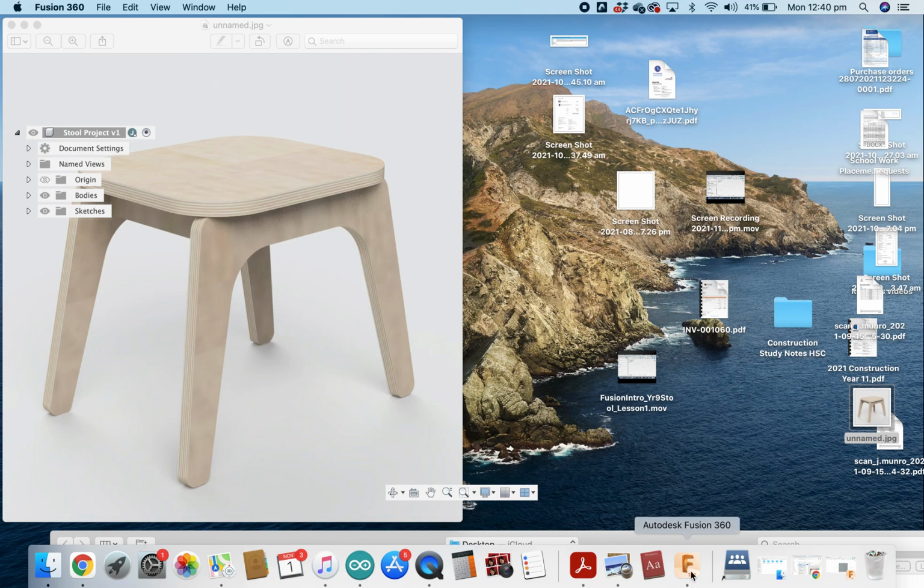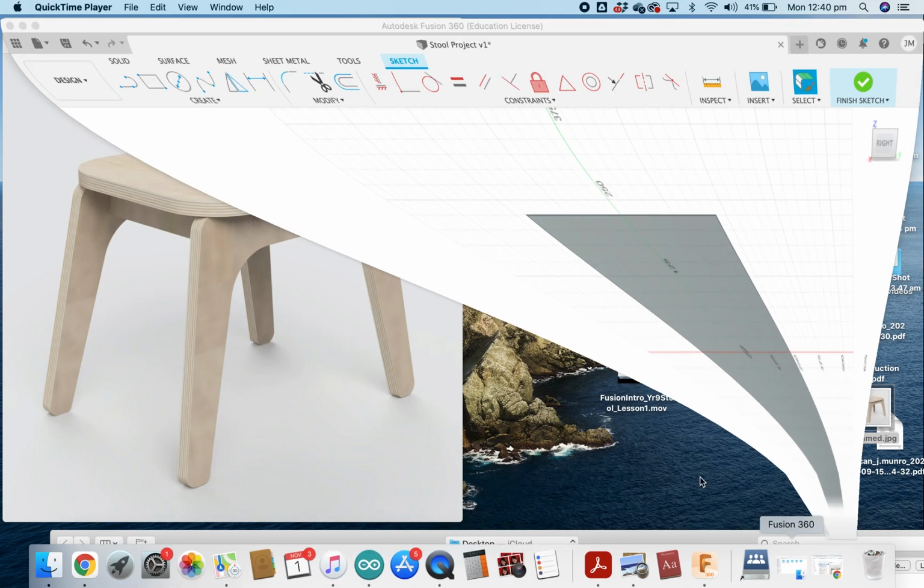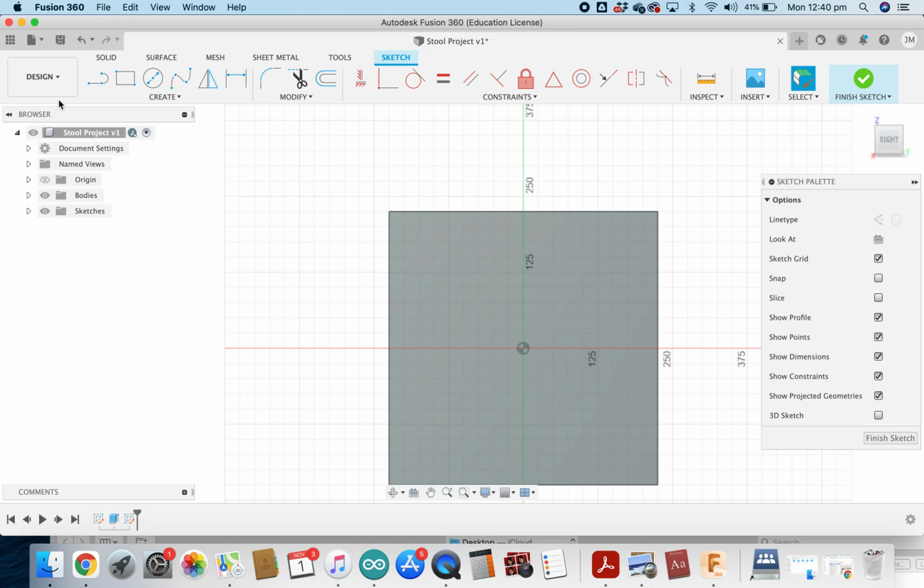So today in Fusion, if I just pull that back up, we've created a sketch, and the sketch we're going to create is a line. So we're going to draw a line on our surface of timber here. You can press L for line, or you can select the line tool in the top left hand corner. And then we're going to select this little triangle or arrow over here on the right hand toolbar. And what that does is it means that we'll be drawing construction lines.